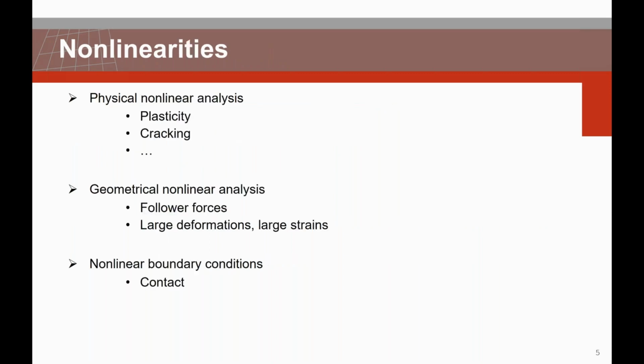In terms of nonlinearities, in general, we might classify them as follows. The physical nonlinear analysis, such as plasticity or cracking, geometrical nonlinear analysis, such as large deformation. That would be the case of our demo today. But it can also be nonlinear boundary conditions, like we have in contact analysis, for instance.